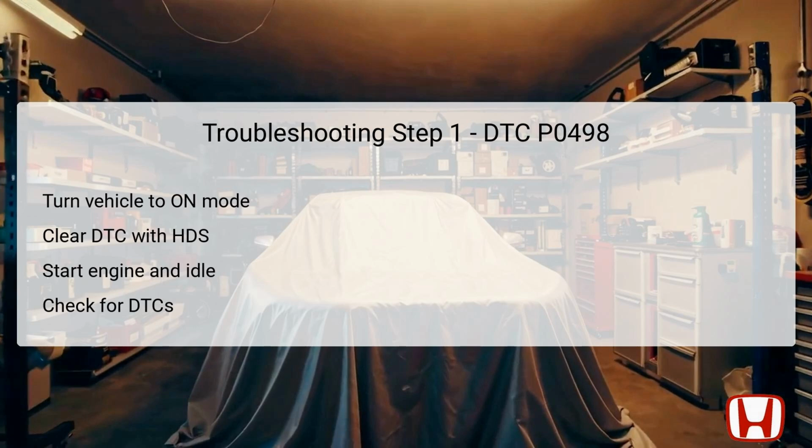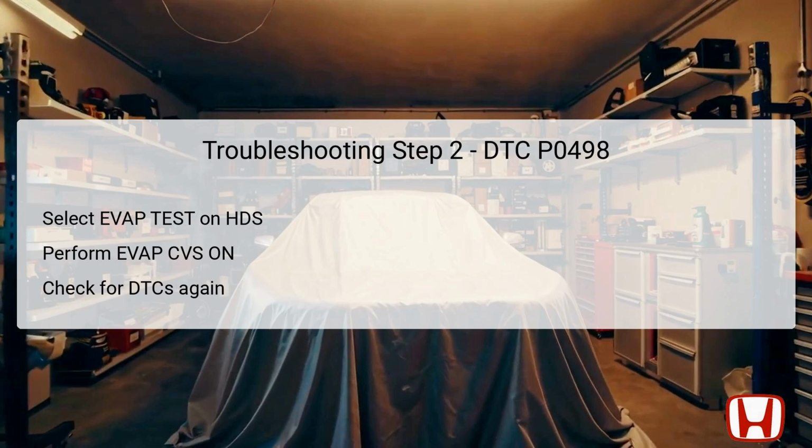Step 2 focuses on further confirming the operation of the EVAP canister vent shut valve. Using the HDS, select the EVAP test option from the inspection menu, which allows you to access detailed diagnosis of the evaporative system. Conduct the EVAP CVS on test in the single solenoid mode. This helps to engage the valve directly for testing purposes.